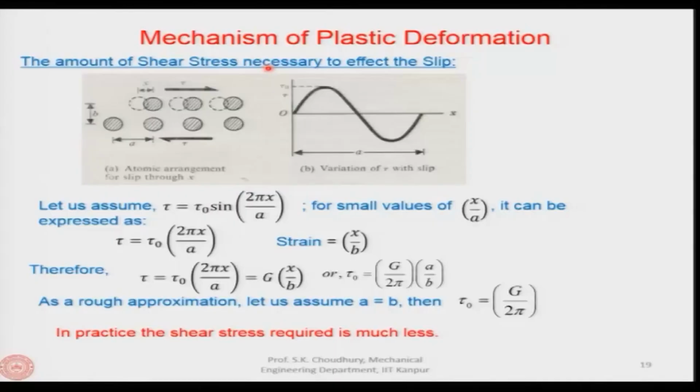This is how we can understand the elastic or plastic deformation on the atomic scale, when we know that in a lattice structure the layers of atoms move or slip past each other, which is called the deformation. Now, this deformation can be either elastic deformation or plastic deformation. As we said, elastic deformation happens when the load and extension curve is linear, and if it is non-linear, beyond of course the yield point, this is the plastic deformation.